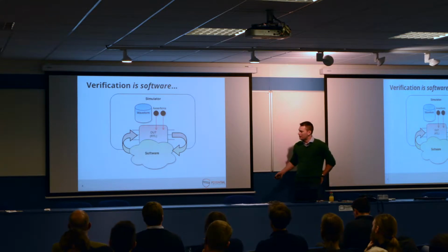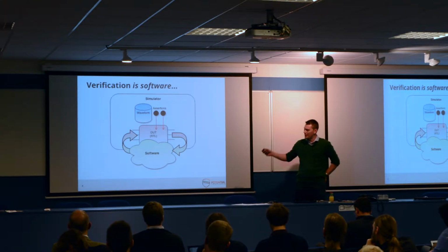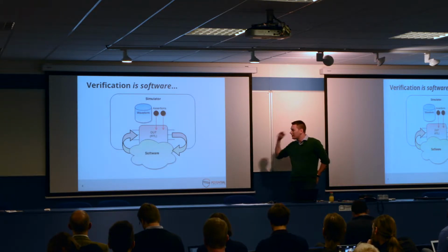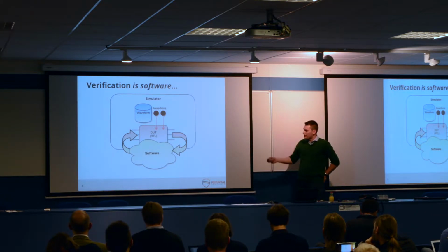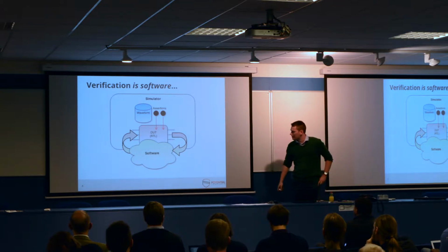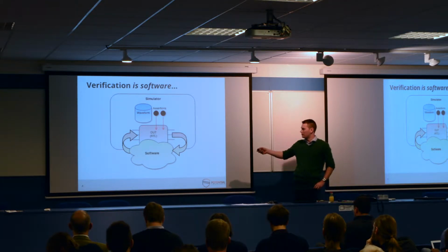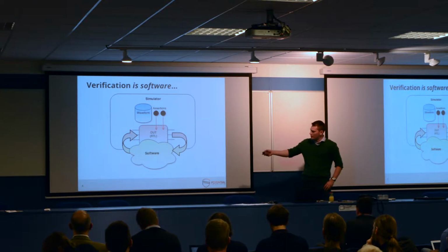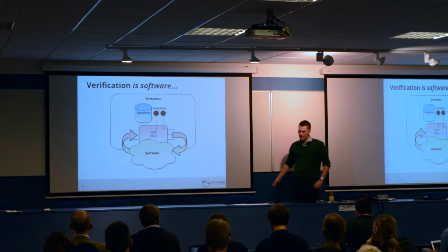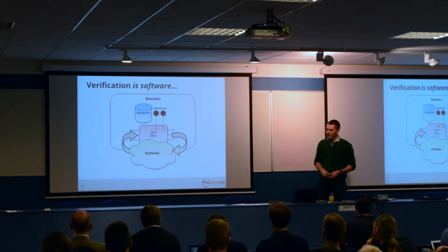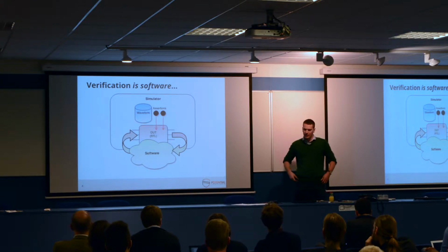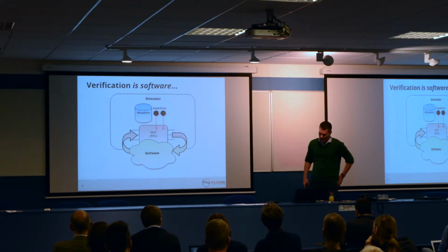If we look at your typical verification flow, you have some simulator. I should stress that this is functional verification in simulation. So you have your design under test, which is running inside a simulator. The simulator might provide some kind of waveform, assertions, debug capability. But then you use something to stimulate the inputs of your design, to check the outputs of your design, validate that the behavior is what you expect, and that's entirely software. So that's obvious, but surprisingly radical for some reason.